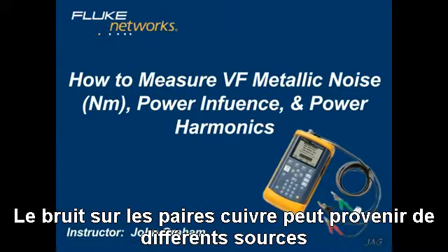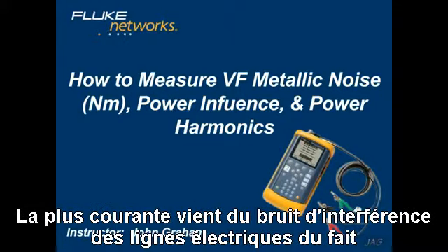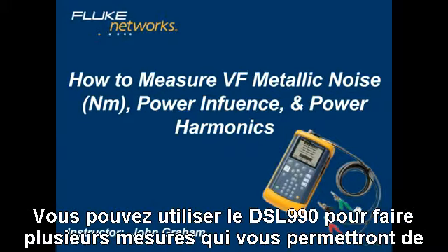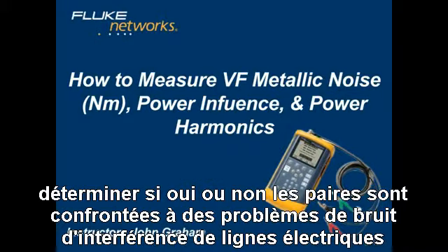Noise on copper pairs can come from a variety of sources. One of the most common sources is power line interference noise due to the simple fact that telephone lines are very close to power lines. You can use the Copper Pro to make several measurements that will allow you to determine whether or not a pair is suffering from power line interference noise problems.